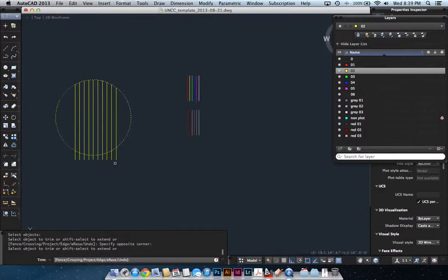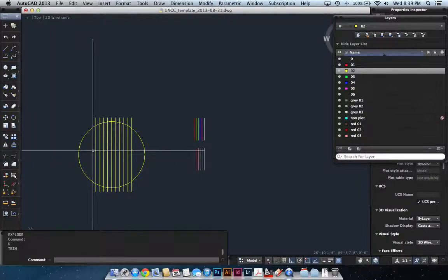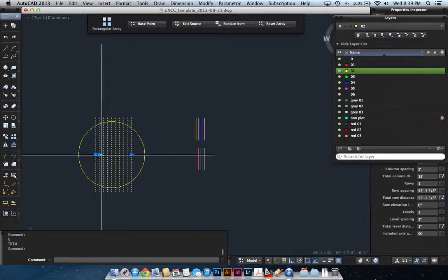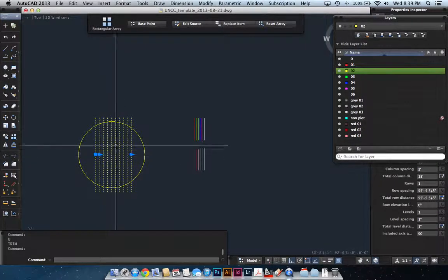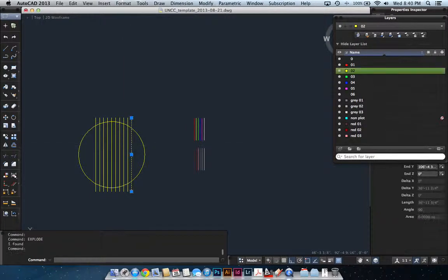and I can go and select my surface and trim again. So again, I'm going to go back and undo to when I had the hatch. You notice how it doesn't have a series of grips and nodes. It has almost a hatch kind of quality to it where there's just a bounding beginning and end piece. That means it's a smart object and therefore not necessarily trimmable because it's not just a series of simple vectors. To get it that way, you just explode, which is literally typing in that command or using the icon, but if you explode that, you now have individual lines.